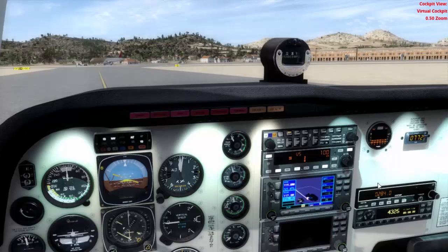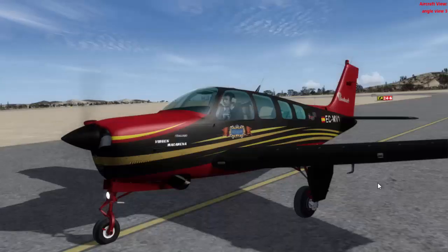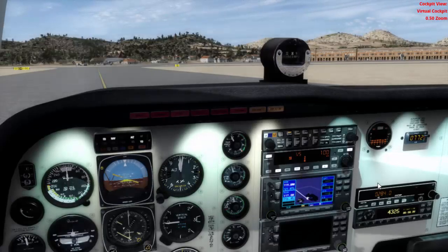We will go to the platform, we will park the aircraft, having in mind all what we did before, having in mind that we did the descent rate that was indicated in the table. Remember that the descent rate you must follow is always according to your recommended landing speed, and also we have to decide if we land or not, because we have a point that is called MAPt, okay, that is also indicated in the IAC chart, instrument approach chart, and that point is telling us that if we see the runway we must land, but if we don't see the runway we must miss the approach.